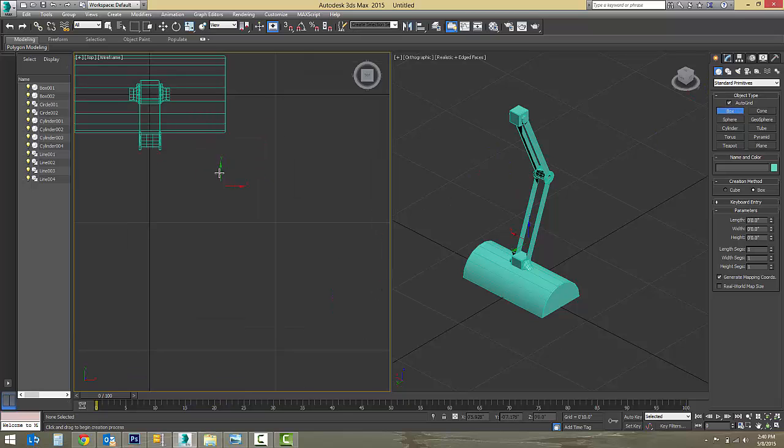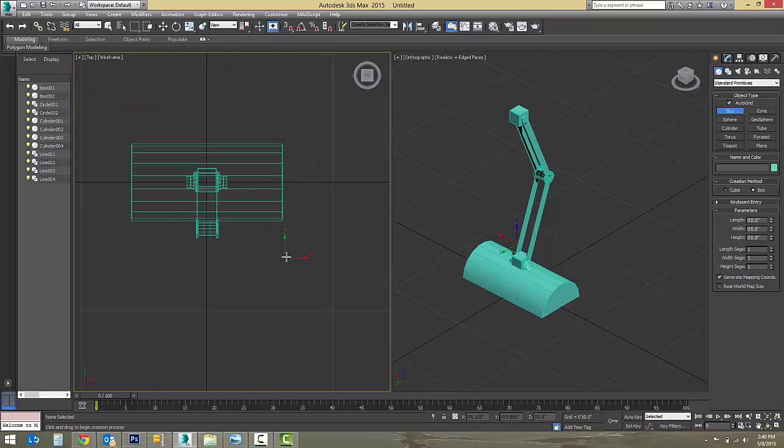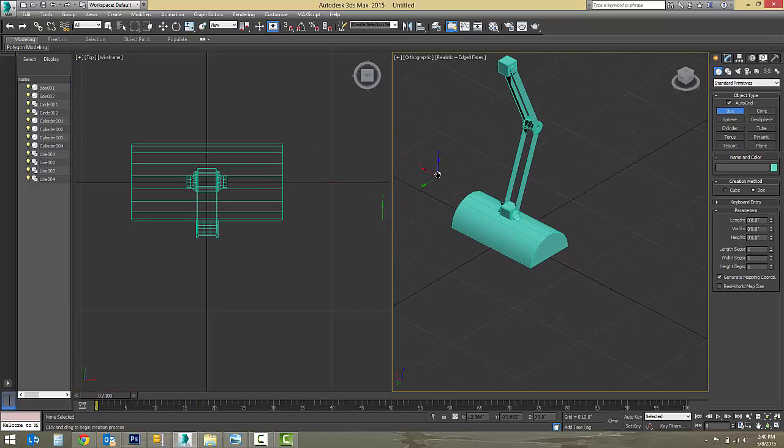I'm going to take Auto Grid off. You can tell that Auto Grid is on because this is called a gyro. It's the XYZ button. It's following the mouse, and if you move over objects, it'll change its orientation. That's telling me what orientation my new object would be created at. So I'm going to turn that off, and now that's off, I just have a mouse button.